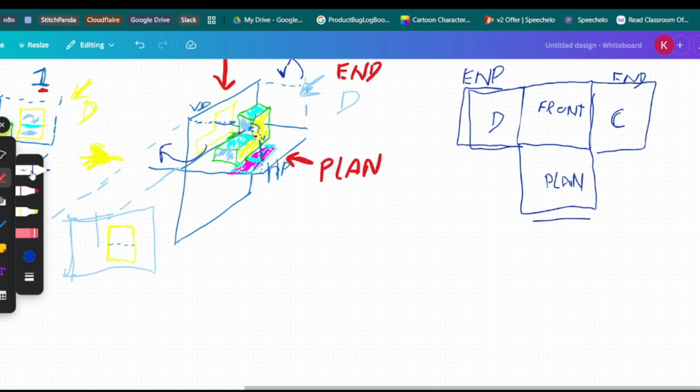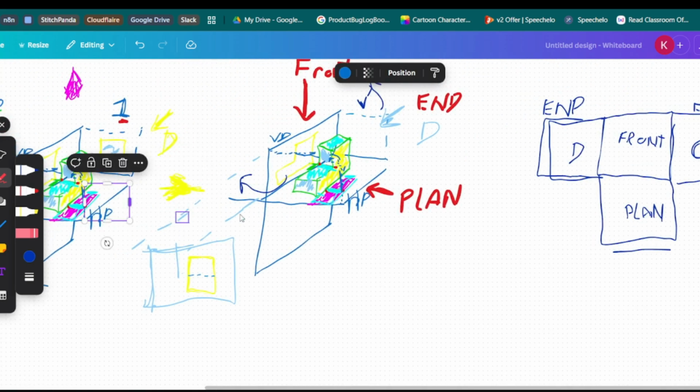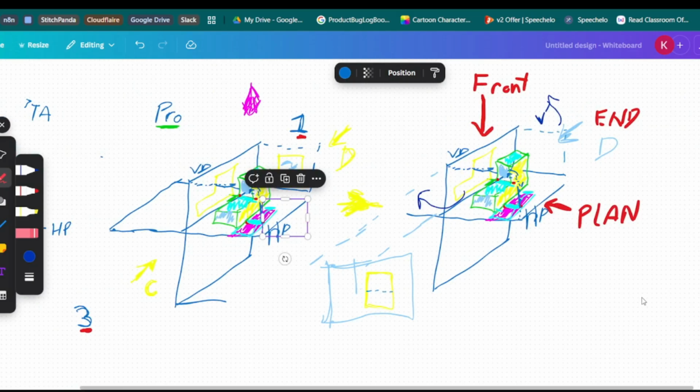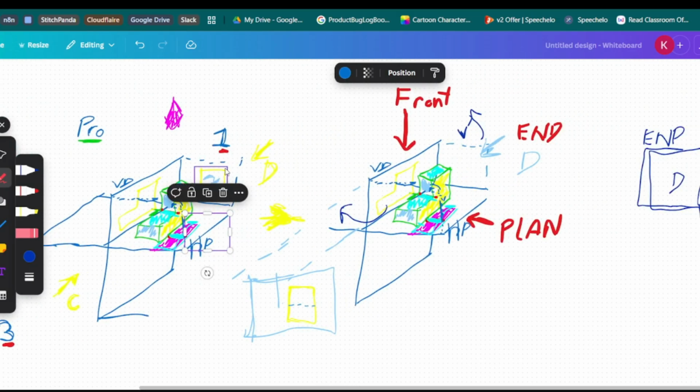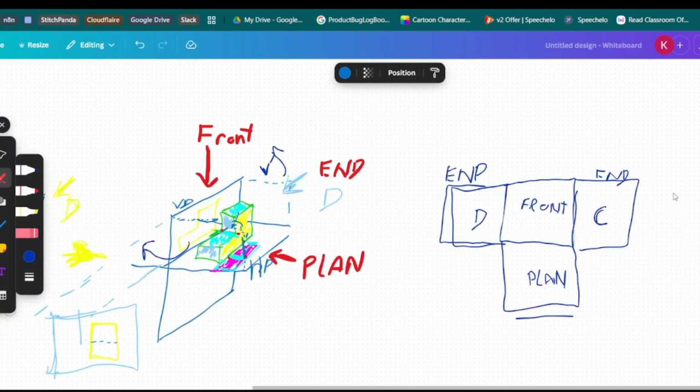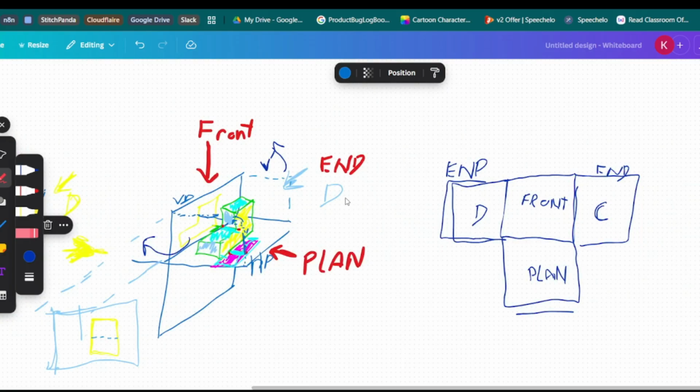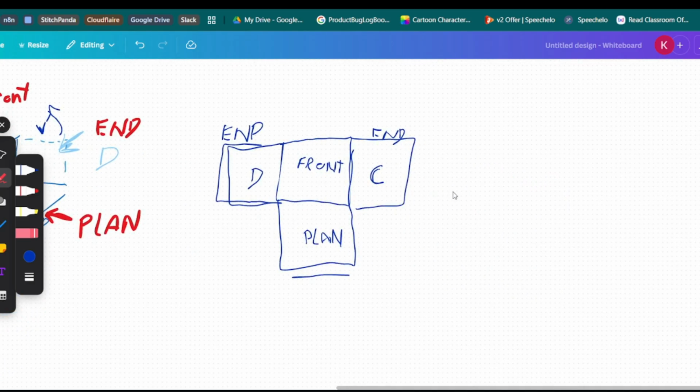Again, we're gonna reference the drawings that we did before with the C and D. So where C projects onto this one, when we fold it open, this will be the C screen here. Where D comes looking from this direction, it's on this screen, so it's gonna actually be projected here. Another important thing that I want you all to note, especially when drawing either first angle or third angle projection, will be your 45-degree transfer lines here and here, which is important.